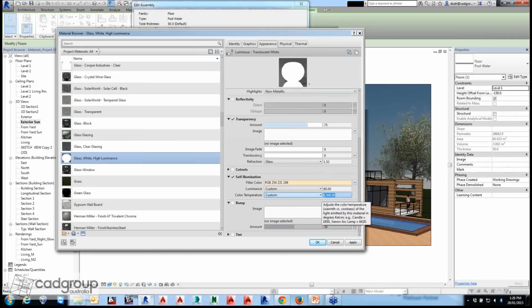Now, for the example of that particular light, what I have used was just a value of 60 or somewhere. And the color temperature you can change as well, which will be good. So if I'm using 6500, it will be like a halogen look, or the color temperature if I'm changing to let's say around 4000 or something, which gives me a nice clear white glow material.